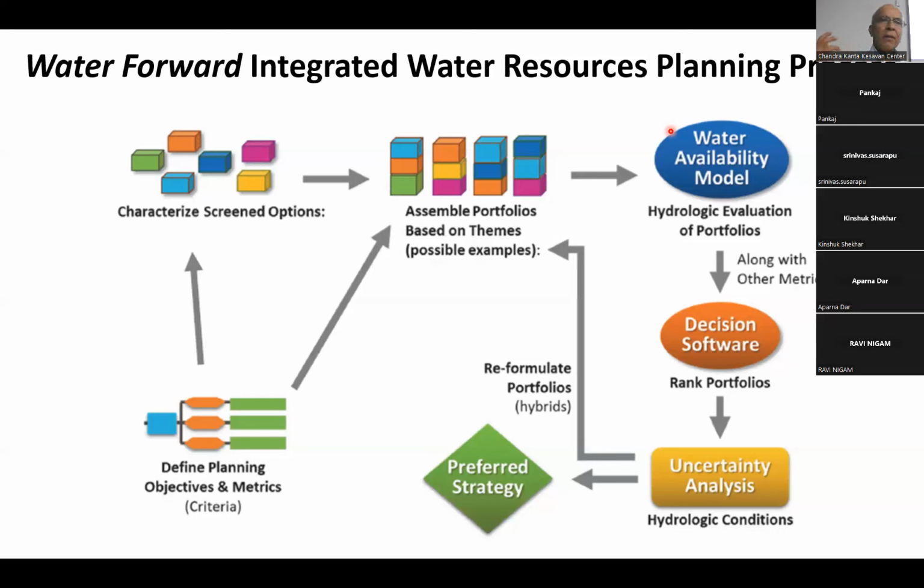So what took millions of years to be collected in the groundwater, we're going to pump it in 100 years, and then after that, what are we going to do? So the only way to use groundwater is if we can put water, good quality treated water, inject it in the ground through an injection well, and then through a production well we can take that. So basically it's like a savings account.